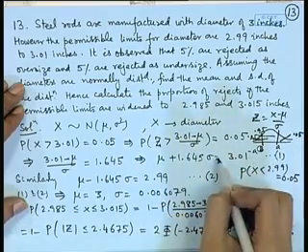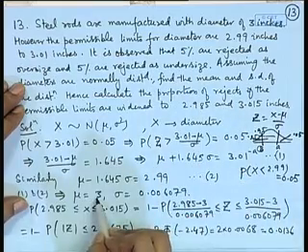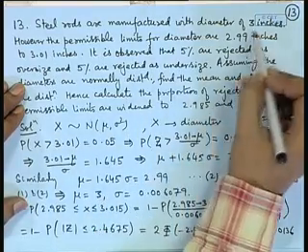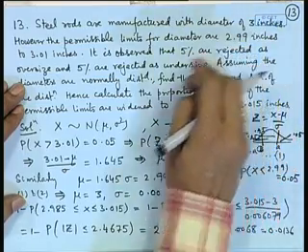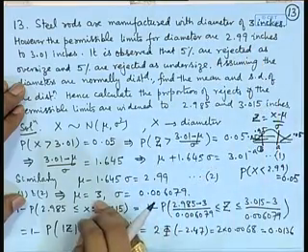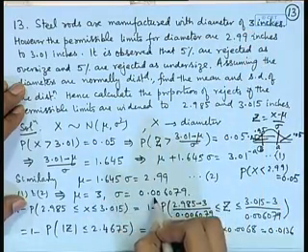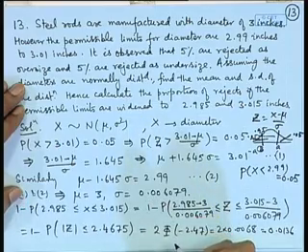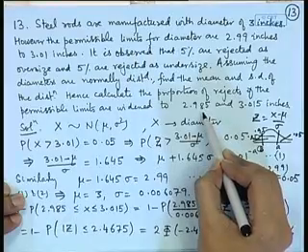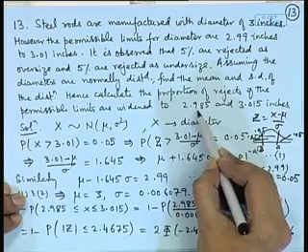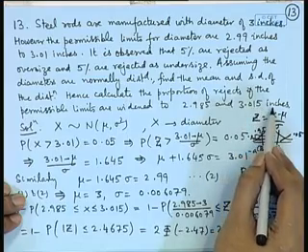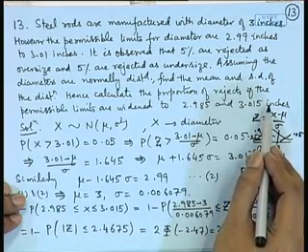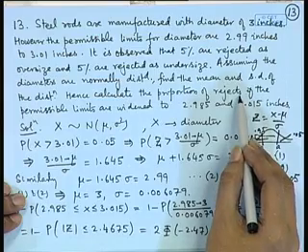So, if we solve these two linear equations in two unknowns mu and sigma, we get mu is equal to 3, which is okay, because the distribution is symmetric, and here we are assuming that it is normally distributed. So, mu must be 3 because that is the target here, and sigma turns out to be a pretty small value, 0.006. Now, under these values of mu and sigma, if we extend the permissible limits by a little more, that is by 0.015, that is from 2.985 inches to 3.015 inches, then what is the proportion of rejecting of the steel rods?